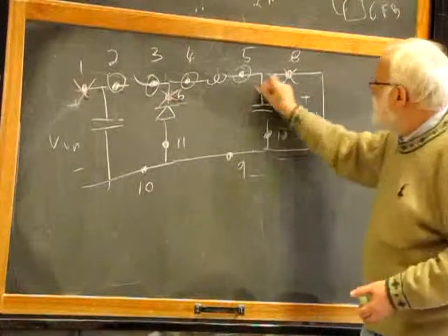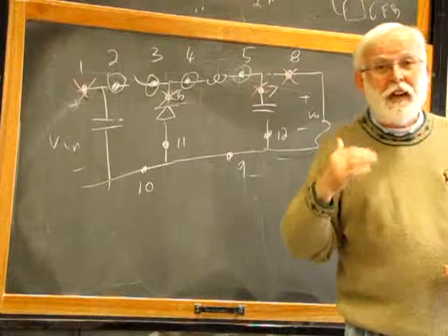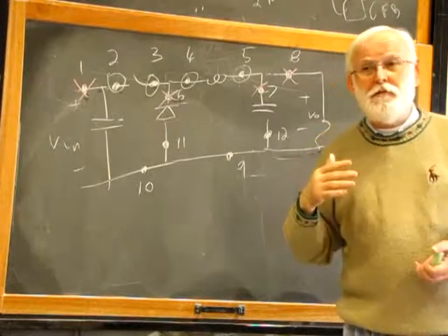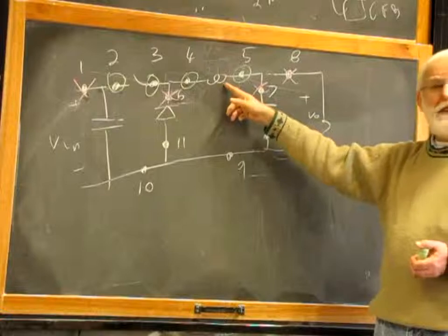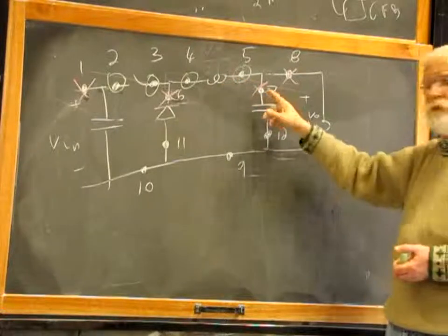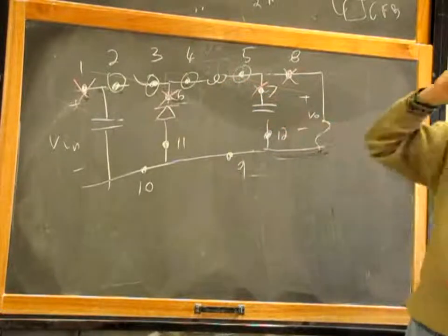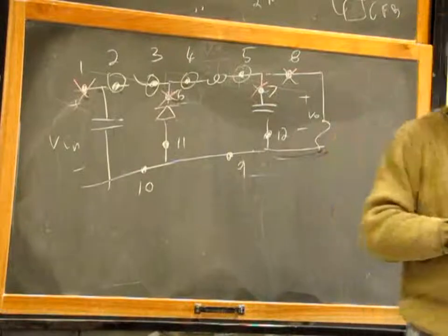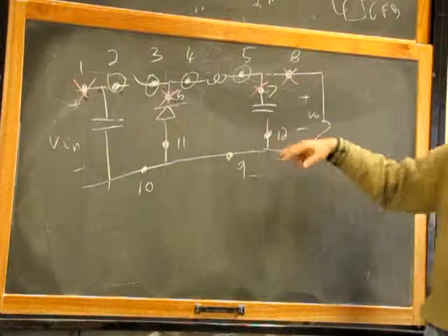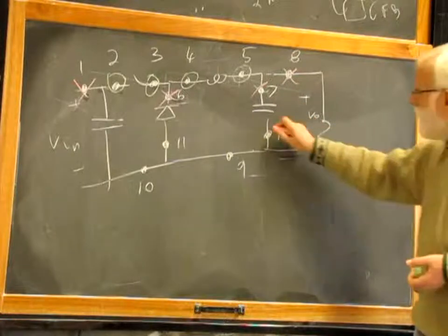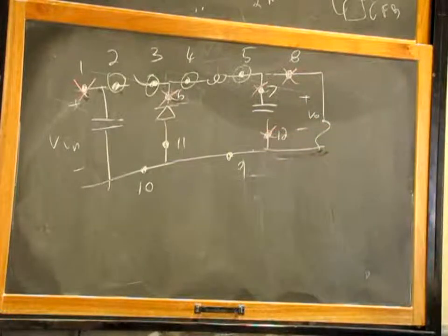So this is a no, unless you have a different way to establish what is the DC current through the inductor. In this case, you could use this one. There are techniques of control like IVI, integral voltage on the inductor, that can use this ripple current, but not a good idea. And this is also not a good idea.